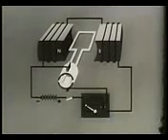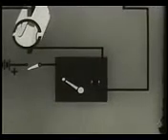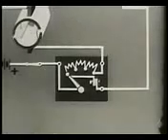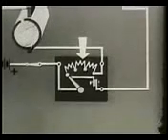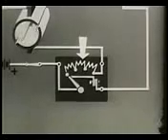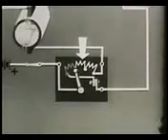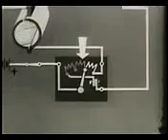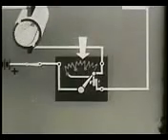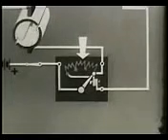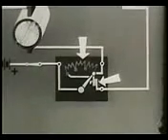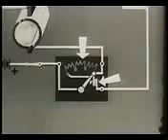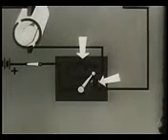Here is a basic shunt motor with its starting box. In the starting position, the circuit to the rotor windings is closed through a series of large resistance coils. As the lever of a switch is moved, rotor speed and CEMF build up gradually, and the resistance coils are subsequently cut out until running speed has been reached. The lever is held in the fully open position by an electromagnet. If for any reason the power should fail or the field coil open, the electromagnet becomes de-energized and the lever is returned to the starting position by spring action.